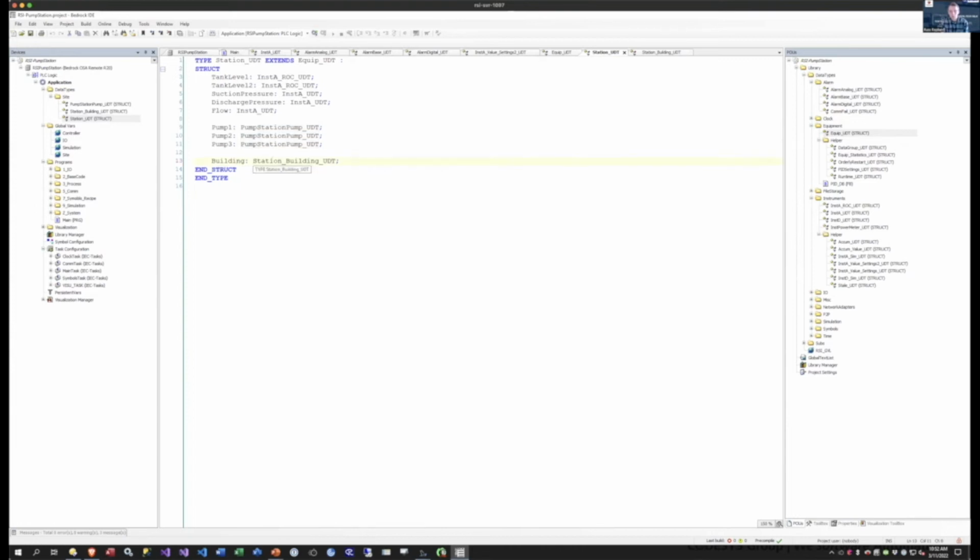And you can build these out as deep as you want. The beauty of this is when we implement this and we enable our OPC server, it actually shows up as a tree when you browse this object. And I can show you that a little bit later as we dig in. So it really makes organizing this data and bringing this data to your SCADA system really nice and organized in a kind of a tree type fashion.